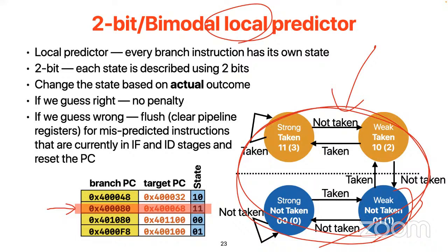The maximum value that a 2-bit saturating counter can express is 3, and the lowest number is 0. So the number would move between 0 and 3 as shown in a state transition diagram. And we set a threshold, say 2. When it's larger than or equal to 2, we predict taken.